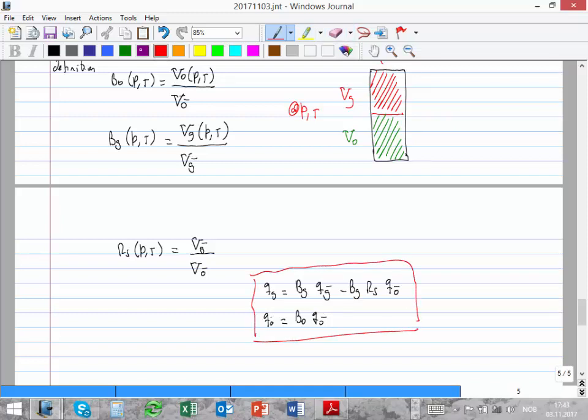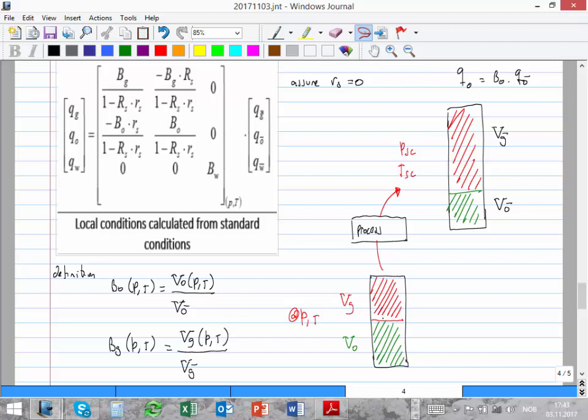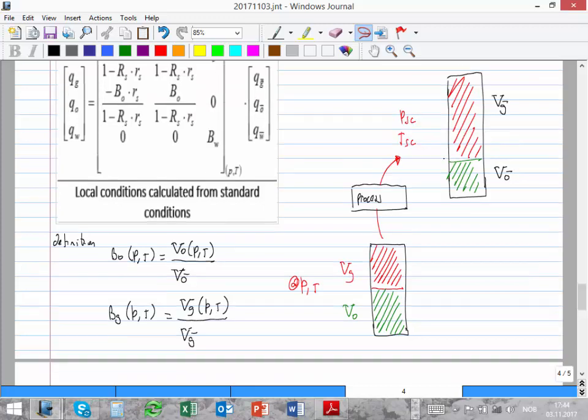And that means that basically the rate of gas at any pressure and temperature is the rate of gas in the surface that I compress. Bg, remember, is taking into account the compression, and this term is taking into account that at a certain pressure and temperature the gas can re-vaporize into the liquid. Actually this gas from the surface came from the liquid. One part came because this gas expanded, but one part came because that liquid vaporized. So that's what I'm doing here.